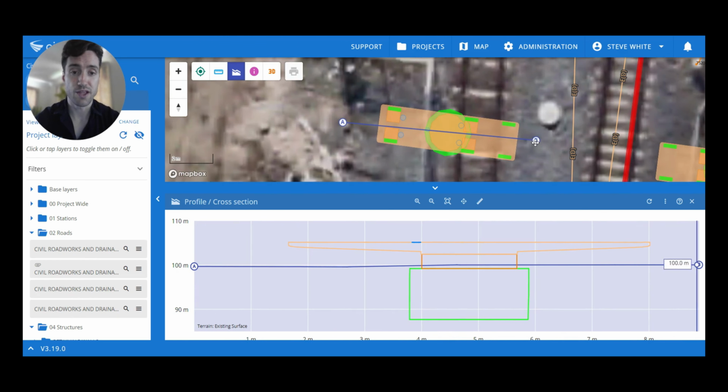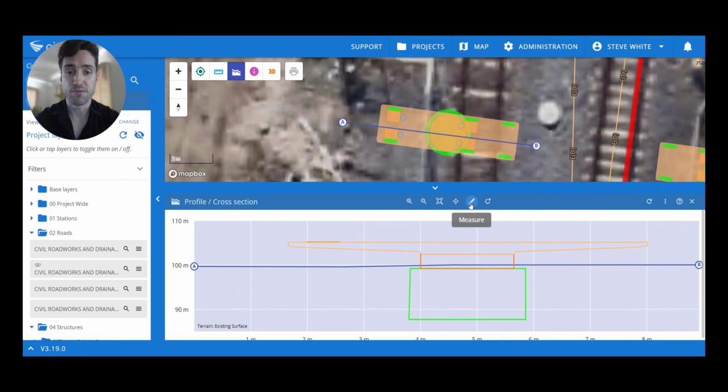If I pull that through there, we've got here a crosshead, pier, and pile sitting from above ground to below ground. Again, they've got that existing surface there as the reference point. And also just to point out here, this measure icon on the cross-section panel itself. I can do measurements within the section here, and I can lock that on as it turns red there. It's locking onto the feature in the cross-section panel here.